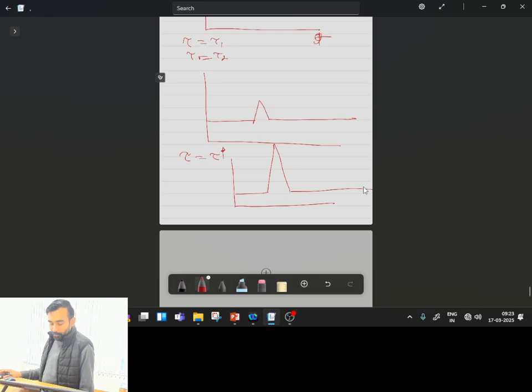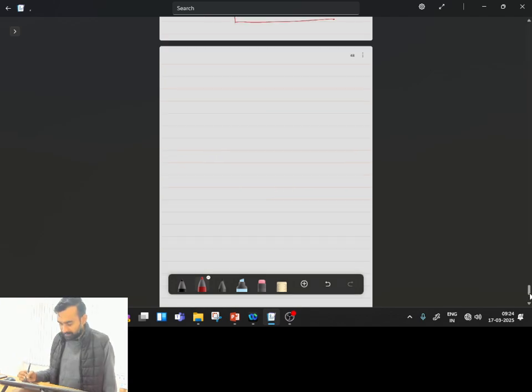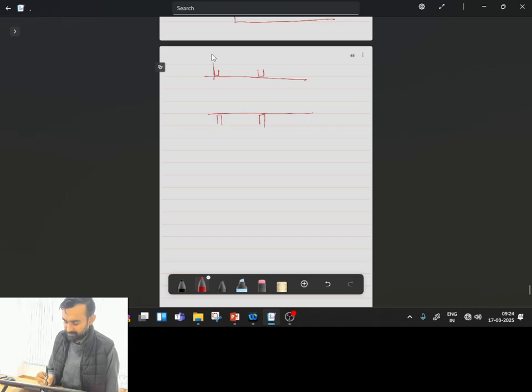Okay, now this mathematical analysis we can employ on random signals during multi-phase flow measurements, and with the help of these measurements we can try to determine the velocity of the dispersed phase particles present in the system. So what I can do is have a pipe something like this, and in this pipe say I have some laser and photodiode, and at another location also I have a laser and photodiode. So this is location 1, this is location 2.